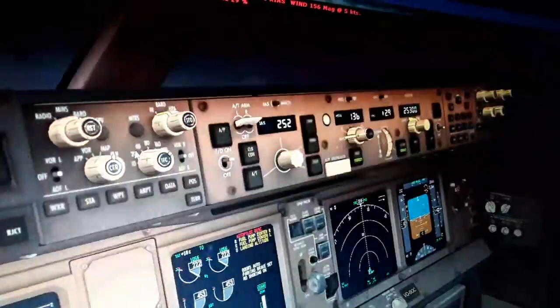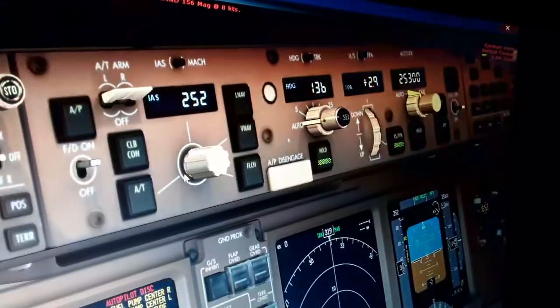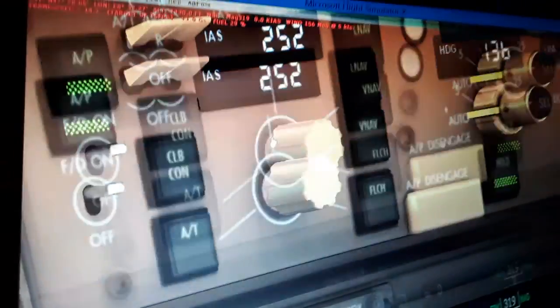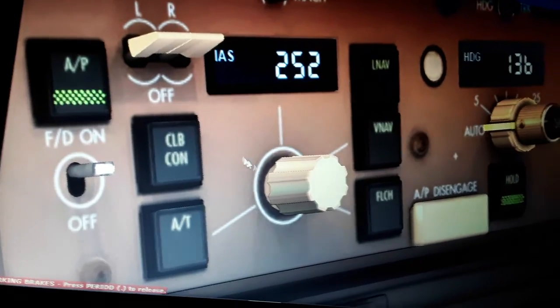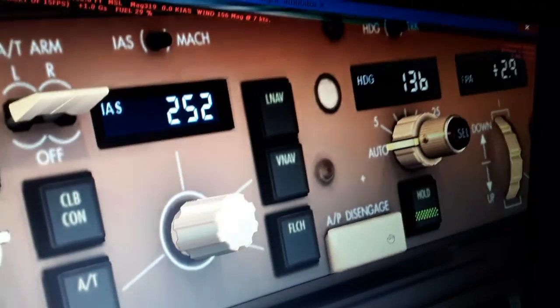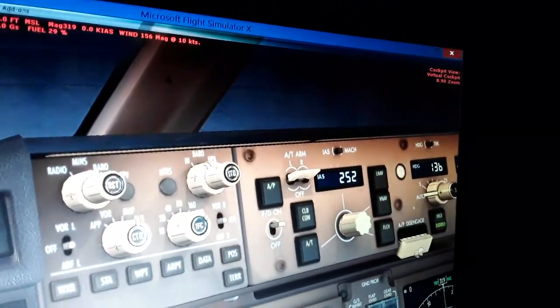So we have the autopilot engaged again, so we can disengage it like this, using this button here on the control wheel of the airplane. So we have the autopilot disengaged, disconnected again. We cancel the warning if we like and reconnect it. So this is how to engage and disengage the autopilot. Engage here like this, and disengage here like this, and then cancel the warning.